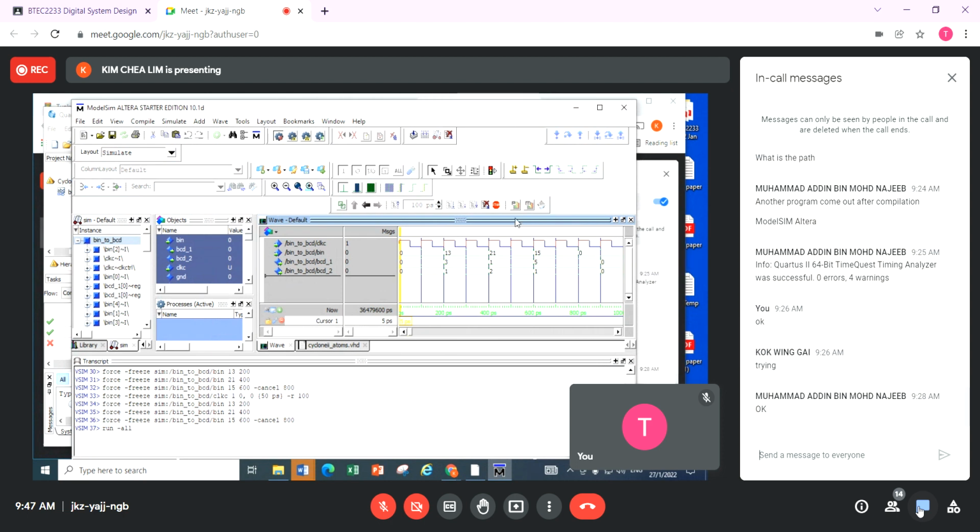So this is a waveform that you are going to see. When you are doing your simulation, you are going to find that the background is black color. So you change your background color, especially when it comes to report. Go to tools, follow page 16. I teach you how to change the background color to white color, and also put in this label. If you don't see this part here, you put in this label.